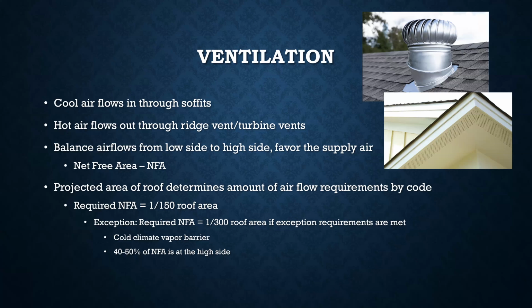Then, as they learned more about how to handle airflow, they figured out that when you put holes in your soffits that overhang the house, it's going to let air into your attic. And if you put holes near the top of your attic, it's going to let the air out of the attic. The roof is being cooked by the sun, radiating all this heat down into your attic and heating up all the air. That air is going to want to go outside because it's warmer than the outside air, so it's going to go out those air vents.